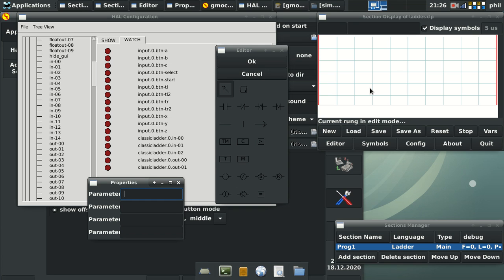In the case of one of my machines, I was using a physical relay to switch between my tool setter and my spindle setter, where now I can use ladder logic to switch between two inputs on my G540, or in the case of my new machine, my Mesa card, I will use two inputs and toggle between the two of them with Classicladder to monitor which probe is being used at any given time.